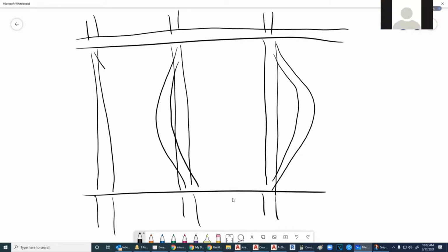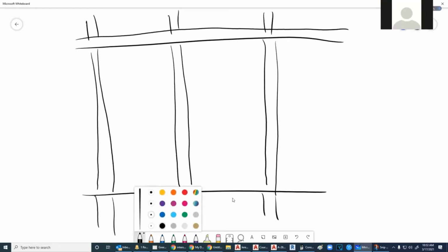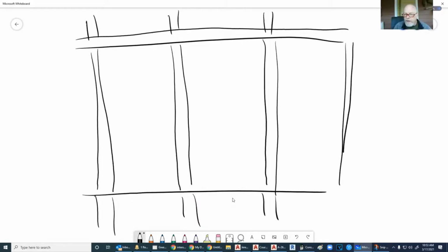Absolutely. And when we're relying on a 4x8 sheet of plywood, often if it's only going to catch the middle part of those two outside studs and you're relying kind of on a toenail of a sheathing nail, you don't have as much structural capacity in each sheet as you would if it was crossing 4 studs. Right. So when we're talking about doing the 2 foot on center, depending on most of the time, okay,